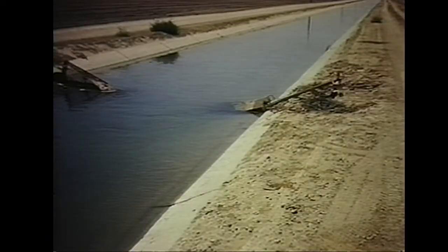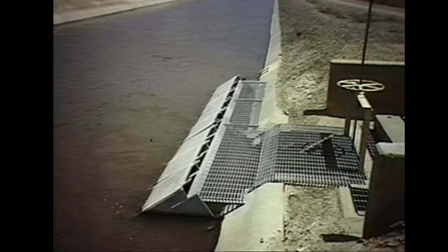A simple grill of vertical or inclined bars, spaced several inches apart, is often used as pre-filtration on canals. These grills can quickly plug and may require frequent cleaning, as often as every hour in some cases. In Grand Junction, Colorado, local Bureau of Reclamation engineers developed a new design. It is a long steel plate with 3/4-inch holes. It is designed with an entrance velocity of less than 1/2 a foot per second.